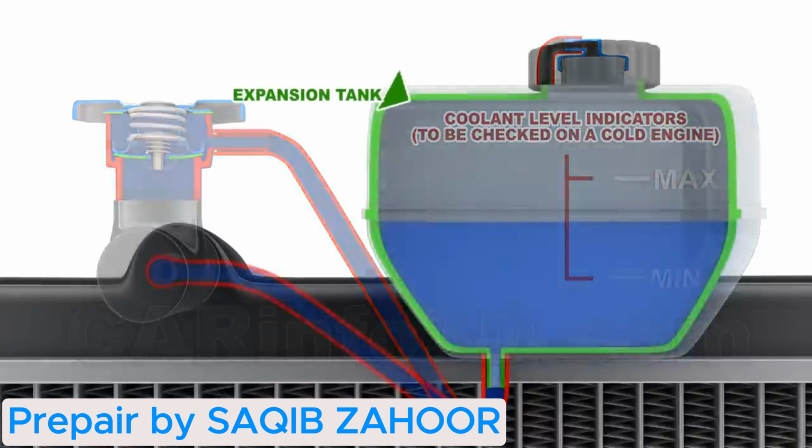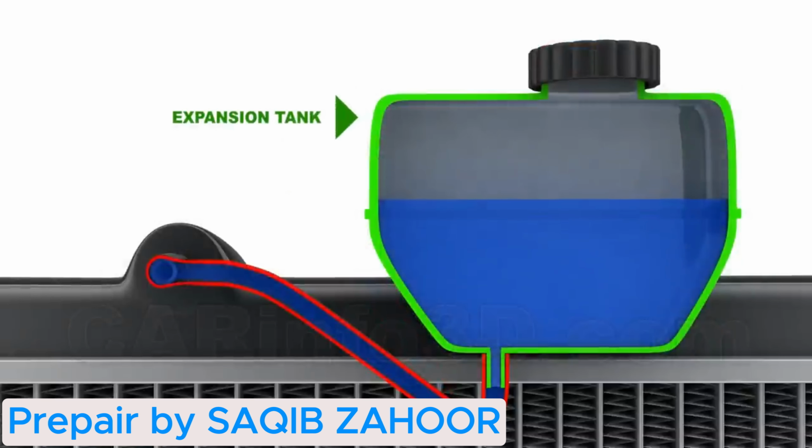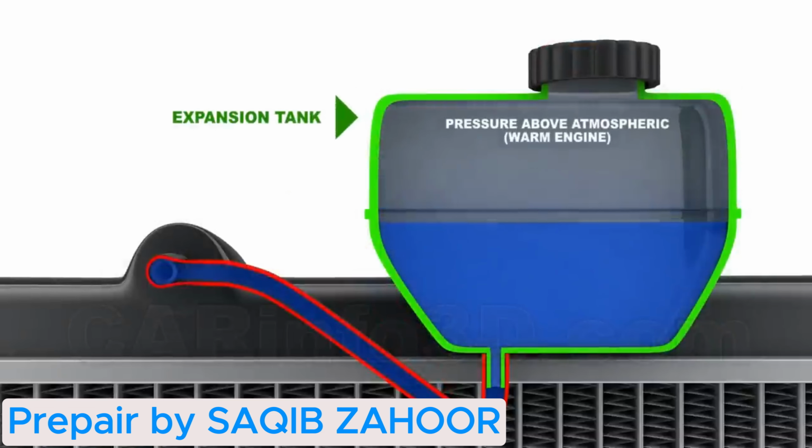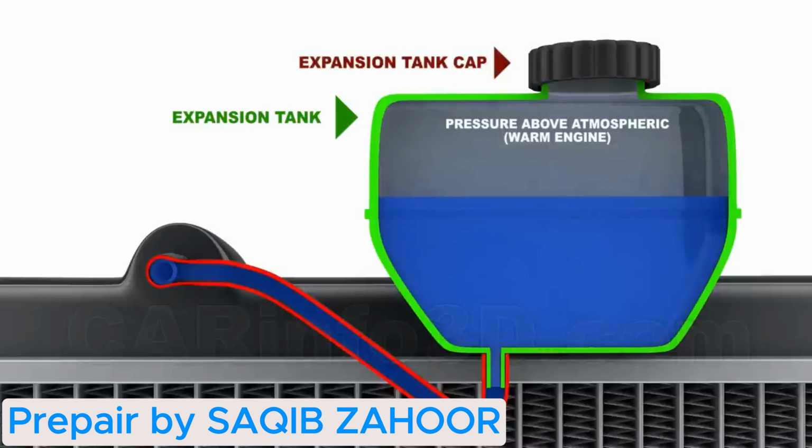This is another design with no radiator cap. Pressure relief is provided in this case by the expansion tank cap, which manages the pressure level in the system in a similar manner by releasing and sucking air.